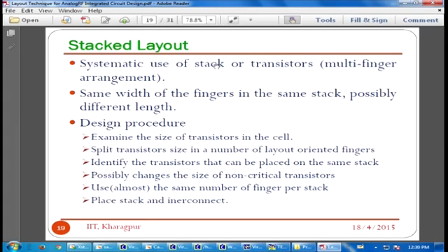Actually, for metallization, there is a design rule that says 75% of the layout should be metal. That is given by the foundry. So if your total metallization is, say, only 55% or 65%, then you will get a DRC fail. That means the 75% rule for metallization is not obeyed. Then what you have to do?